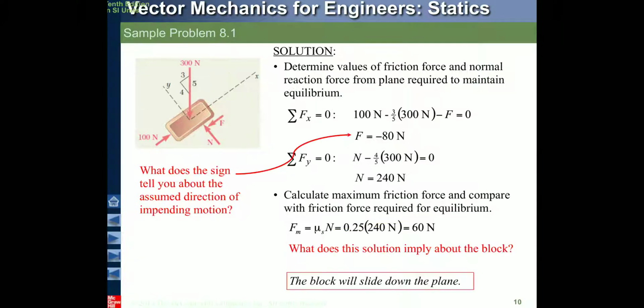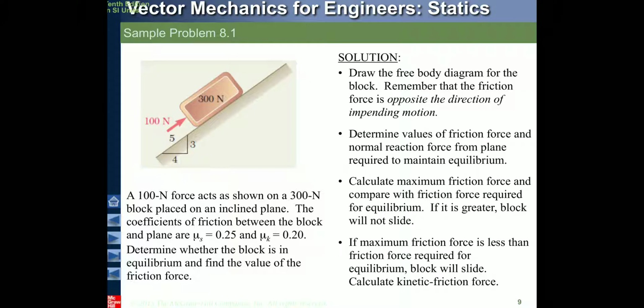Okay, free body diagram. So see, this is a free body diagram. Free body diagram means we have to represent all the forces. Here weight is acting, right? Weight is acting towards down, then the 100 Newton applied force, then normal reaction will be created, in the opposite direction, 90 degrees to the supporting surface.